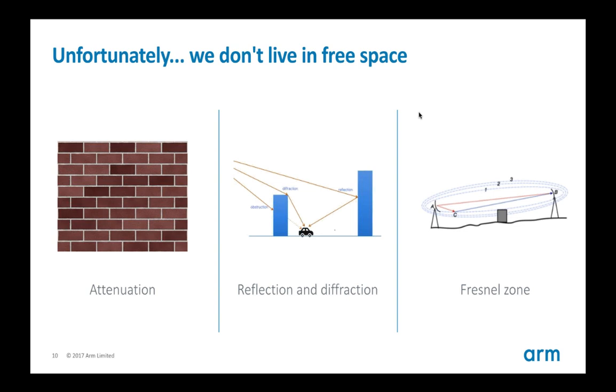There's reflection and diffraction, so that gives multipath signal from your device to the gateway or the other side. This might actually be good if there's only one way of reaching your device, and that's through reflection. You can actually reach the device without line of sight. However, if you have one direct signal and one reflected signal, the phases of those are inverted, and you can actually fade out the signal, even though the signal should have been really good.